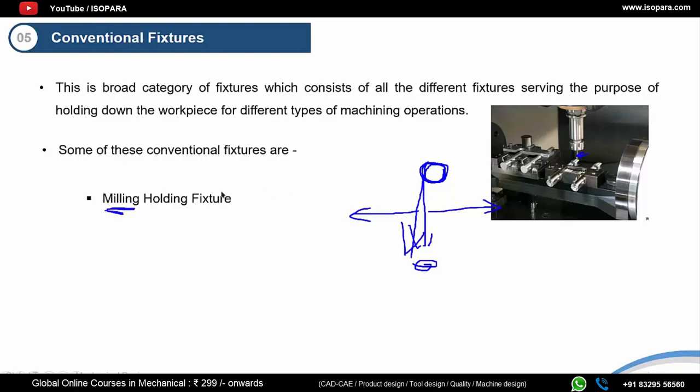This is the basic difference between drilling and milling. If you ever get confused, with drilling you can only create simple holes in the vertical direction, but milling on the other hand can be used to create a hole as well, just like drilling. In fact, on most milling machines you can fit your drilling bits to create the hole as well. But in milling you can run the blade in the horizontal direction or use the sides of the blade to remove material.